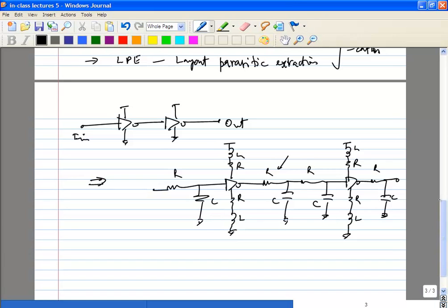Okay, simple case, you just take any amplifier, any large signal amplifier, even an inverter, let's say. If you add a large inductance, which is definitely going to exist in real life, in the supply or ground paths and try to simulate it, you will see all kinds of weird stuff going on. That itself will tell you that inductance is very important.